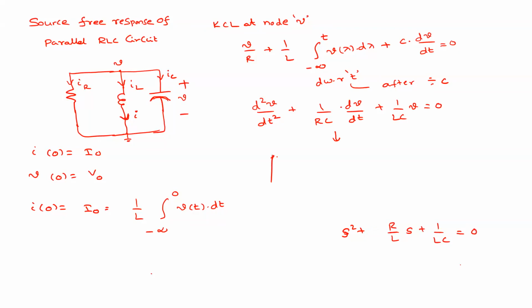Now tell me what is the equation for this in the same manner. Will it be S square plus 1 by RC into S plus 1 by LC equal to 0? Agree? This is its characteristic equation. Will it be its characteristic equation? Yes, sir. Okay.